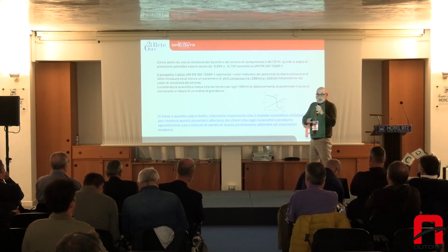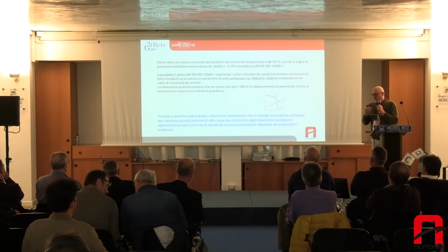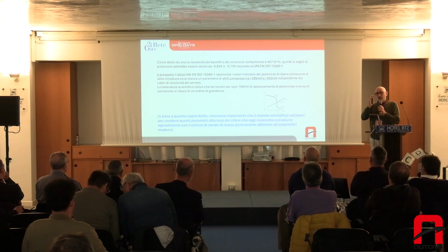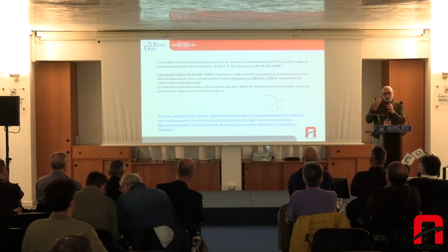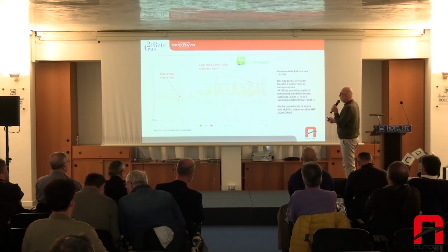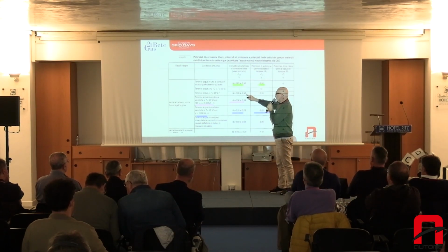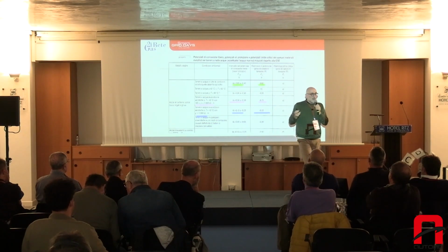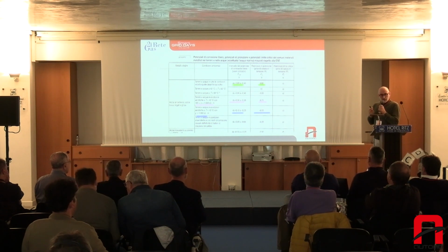Another provocation by Massimo Grigi is the following. If you look at the laws, at the standards, you see that depending on the free corrosion potential, there is a corrosion delta, 400 millivolt. This is another important point, because the law says if you have free corrosion up to a certain value, with 450 millivolt of gap, this is 400. The law tells you that the important part is the polarization that you obtain.